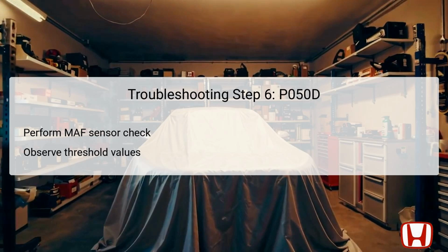If the readings match the threshold, the sensor is functioning correctly, and you can continue to the next step. However, if it fails to meet the specified parameters, replacing the MAF sensor or IAT sensor is necessary to resolve the cold start idle issue effectively.